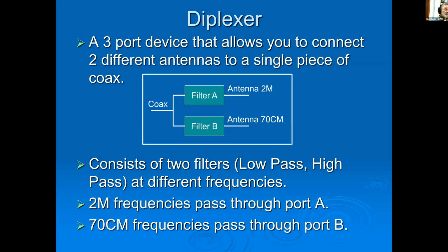So if you try transmitting, like where I have the antenna 2, if you try transmitting into that, you're not going to have the kind of rejection. If you have a separate receiver out here on the 70 centimeter side, it's going to end up potentially getting RF back into it, which could be detrimental to it. So it just doesn't have any real rejection to it.